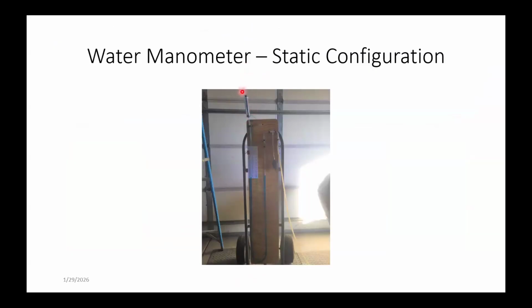Okay. When you're testing your altimeter through your static system, do not pressurize. 6.5 inches of water on here is 250 feet. So you want to be careful with it, but you do not pressurize your static system. The tube over here on the right with the bulb is for use when we're testing the pitot system. And then the tan tube over here goes over to the aircraft to connect into the aircraft.